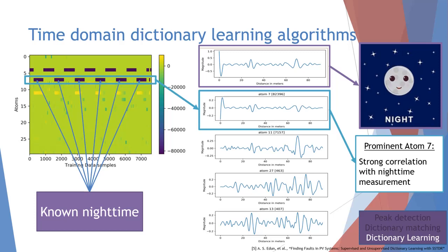Another algorithm was used but not shown. This was called DKSVD. This is very similar to KSVD, but with the added complexity of fault characterization through class identification, meaning this method could be considered a supervised dictionary learning and greatly increases the ability of the SSTDR to be used in PV panel fault detection. The supervised method can actually classify and characterize faults based on the training data set that you feed it, which greatly improves the SSTDR capabilities.